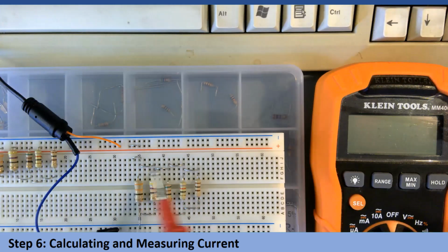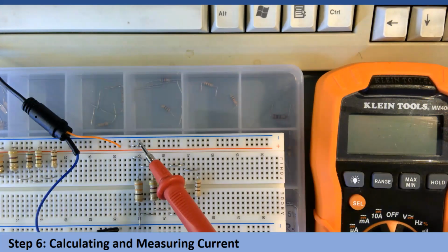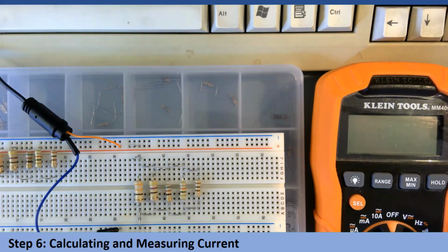I've changed the location of our power rail. It is no longer feeding this parallel circuit. In fact, if I were to measure the voltage, it would be 100% of my voltage supply. I've changed my power supply to send a little more than 4 volts, 4.5 volts. So what I'm going to do, I know I've got 4.5 volts going across here.